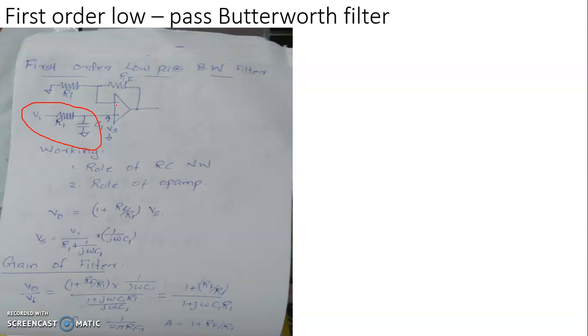For first order Butterworth filter response, that is flat filter response with the stop band having a gain variation of 20 dB per decade, you can have any value for the gain. The gain of this amplifier, as you know, is 1 plus Rf divided by R1. You can have typically any value of midband gain as fixed using this resistance ratio Rf and Ri.